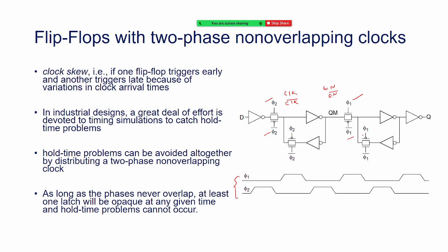Sir, this means we are supplying a different clock now. Clock will be generated inside the cell. Yeah, you have to design a clock circuit also. A clock circuit that will generate a clock, and then you have to put some inverter logic, which will generate the opposite of that, and then these are the two clocks coming here. Is that your question?